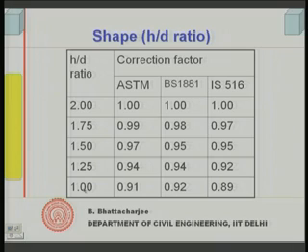This aspect has been considered in various codes, and therefore, say ASTM code or Indian code, it allows you to test cylinders for compression test, even Indian IS 516. Nothing less than 1 is allowed; you have to have 1:2. In special cases, normally we test cubes, sometimes we can test cylinders, but then the cylinder H by D ratio is usually 2. If you are testing anything else, these are the conversion factors.